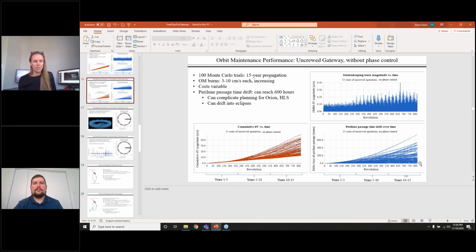And that's what's happening: your phase control has not shifted. Your phase is maintained for these particular 100 Monte Carlo trials, and for these particular ones your phase hasn't shifted, so you're still targeting a baseline orbit that is similar to what you're flying. And so what's going on up with these is that you're in a way different place in the NRHO, and so you're targeting essentially the wrong rev in the baseline, and so your cost goes up because your reference, the baseline, is no longer a good prediction of what reality looks like.